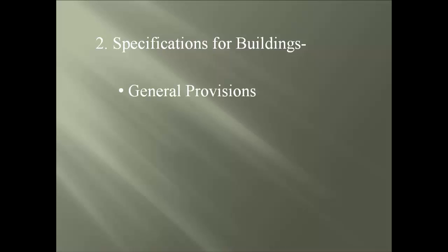First item is the general provisions, which recap the specifications, code, and standard documents that provide industry requirements for the use of material and practice for the design, fabrication, and erection of structural steel buildings that induce both vertical and lateral resisting forces. The specification begins with material that must conform to the ASTM standards.